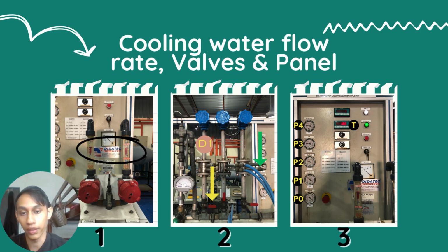When we were done with that, we waited for 5 minutes to take the reading for the second stage compression, and then waited 5 more minutes to take the rest of the readings, which consist of T4, P3, T5, water circuit W1 and W2, air flow rate, input power, T6, T7, T8, and lastly, the exchange water outlet T9.